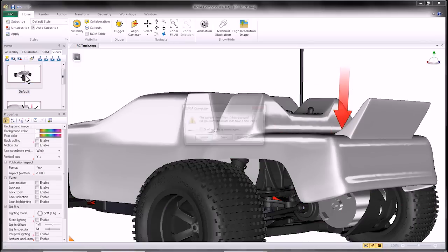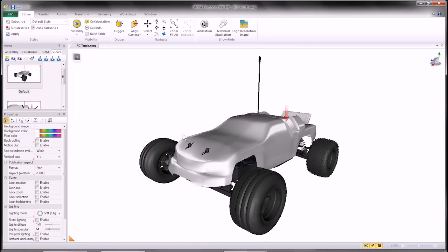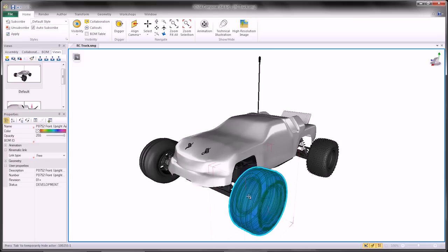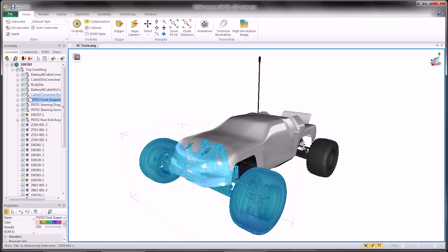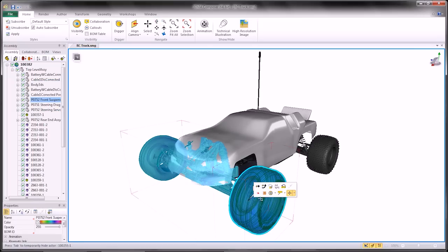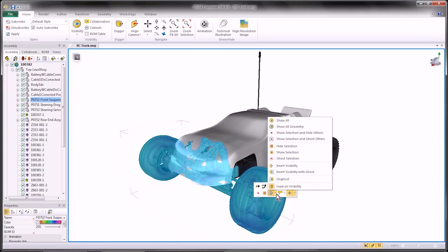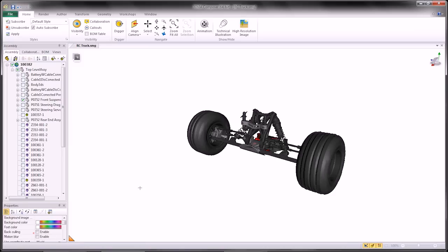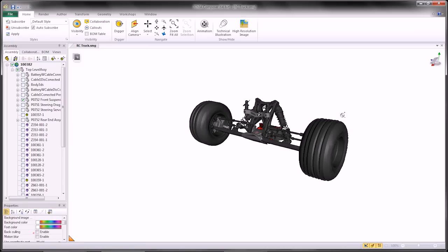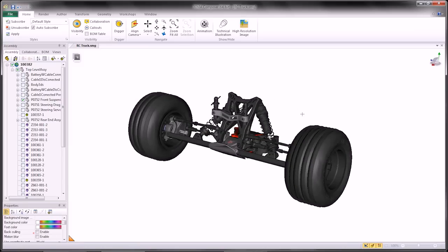Now what I'd like to do is start off by showing you some of the tools that allow us to leverage the 3D CAD data. So not only are we graphically seeing it, but you can see I can actually crawl up the assembly tree. And this is because we have got the full assembly structure straight from our CAD model into 3D Via Composer. So this means I can work with the sub-assemblies as they were set up in the CAD system, but I can also create my own sub-assemblies and part kits if I'd like to as well. So this becomes important when we're shipping different things than what was actually assembled in the 3D model.